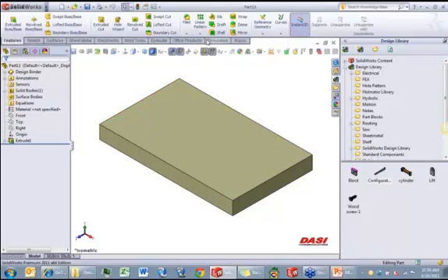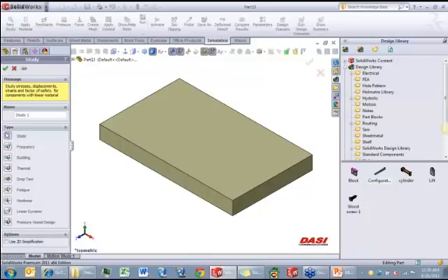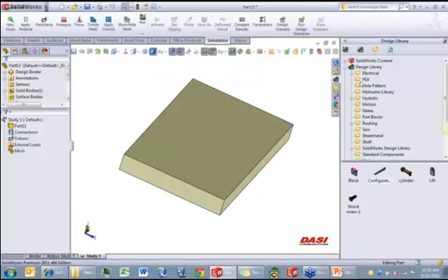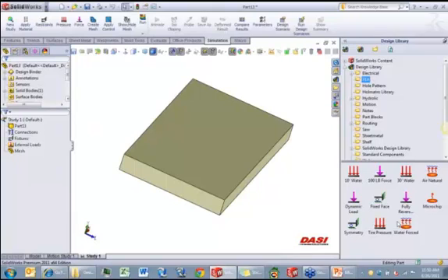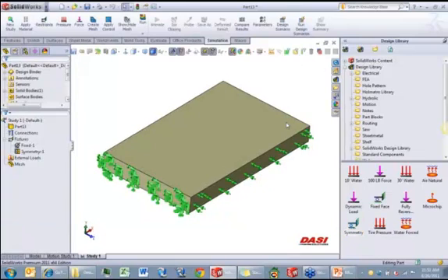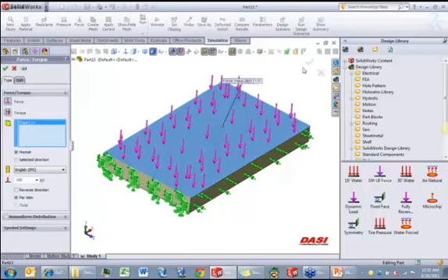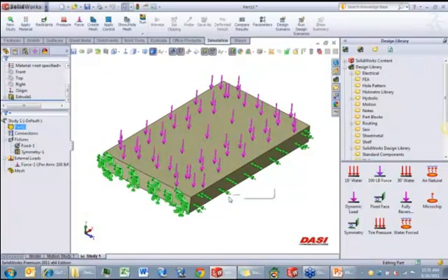For example, if I start a new study for an FEA, maybe a static study, you can drag and drop these loads from existing studies right into the design library. For example, even something like a fixed face. So I can drag and drop that in. Or a symmetry, drag and drop that over to a face. Okay, without actually going to the command. Maybe a 100-pound load. Drag and drop that over, so I don't even have to specify the magnitude. Maybe even other features like 10 feet of water, 30 feet of water. You can predefine these so that you don't have to add the values in when you apply a pressure.